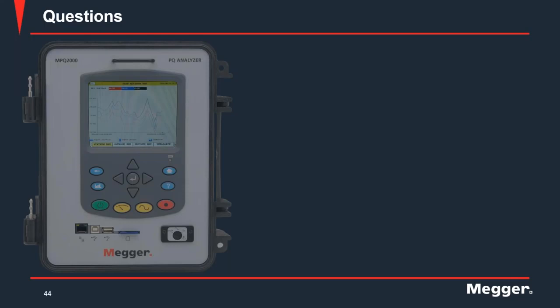One of the key things, though, is making sure that you perform a long enough study. I've seen people go out there and hook up an analyzer literally for 10 minutes and say they didn't find anything. Well, you need to keep it on long enough so that you actually acquire enough data that you can get the analysis, get all the information you need.